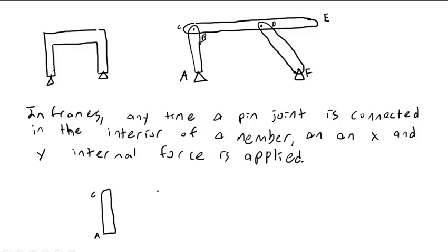Do you remember that one problem a few days ago, I believe on Monday, where we had the things that were like that on the slope? That was sort of an introduction to frames, you might call it. This one actually should be B, if this part here is B and this one over here is C. So this would be member AB. Then we would have member CBDE. So I'm going to draw it, and then I'm going to show the forces on it.